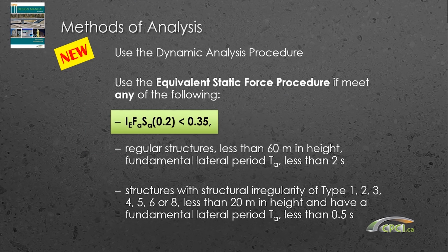And then looking at the equivalent static force procedure, you can obviously always use dynamic analysis, but Chapter 2 goes through and shows the equivalent static force procedure. Regular structures less than 60 meters in height, and following through, as long as you satisfy any of those criteria, you're allowed to use the equivalent static force procedure.